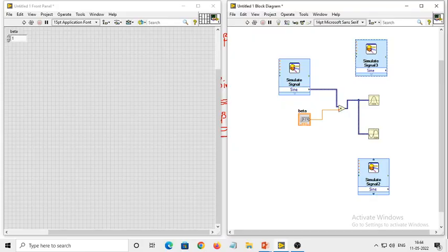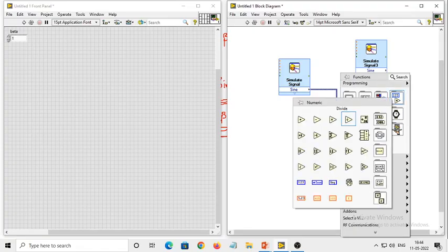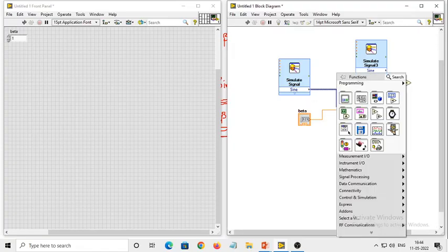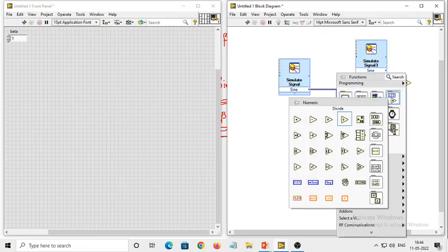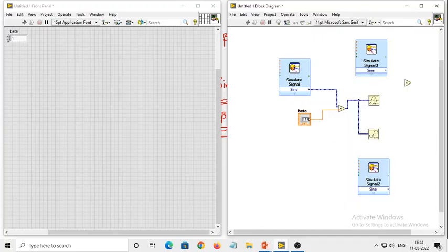Now what you need to do is multiply the outputs of this and also this. You just right click, put a multiplier, and again one more multiplier at the bottom of your screen. Then you just need to give inputs. One input is coming from cos 2 pi fct and the other one is cos of beta sine 2 pi fmt.